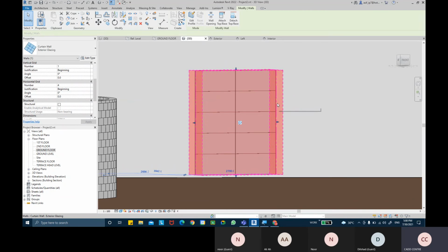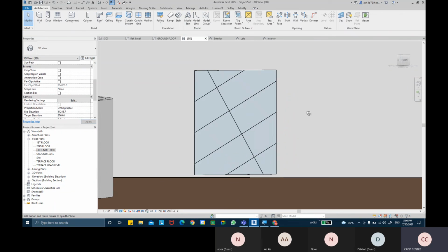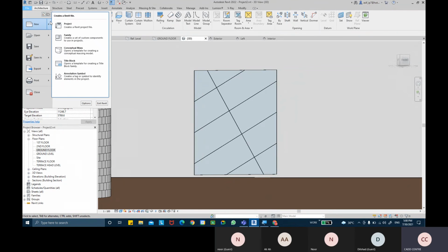Okay, so you can select that panel, and when you come into properties, you have angle options given over here. Angle like that for horizontal, and 30 degrees for another that goes in angle. But this is taking all the grid. For one, you can't. Otherwise, you need to create a family that is called a curtain panel family.